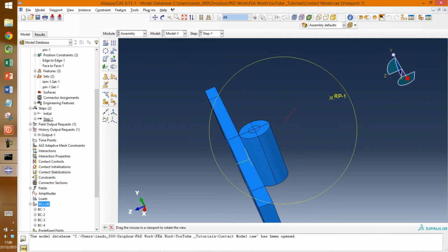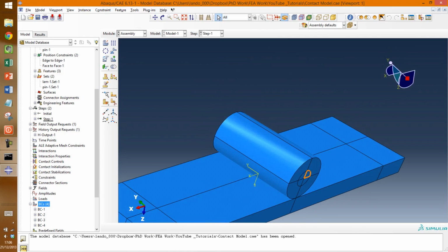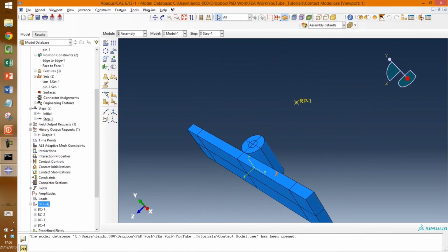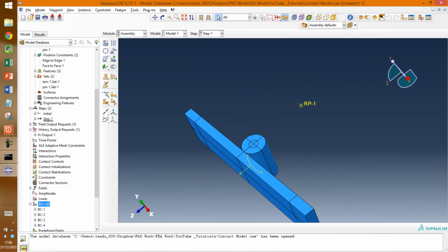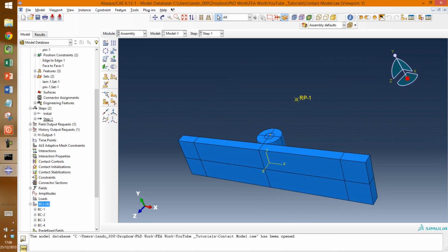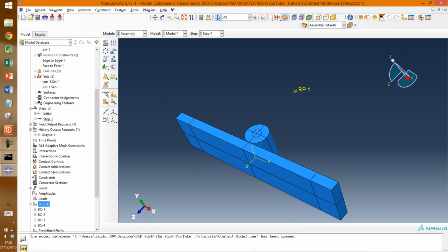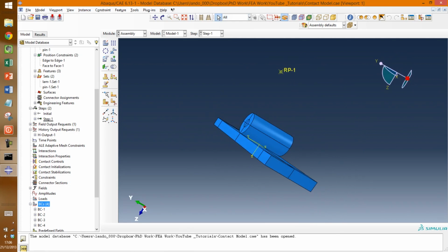So essentially what I'm going to do here is define a relationship between that point and the base of the loading pin. So basically if you tell that point to move 3.5 millimeters in this direction, the loading pin will do the exact same. And I can extract load displacement data from this. So it'll tell me the force that manifests itself on this pin as I'm loading by that certain displacement. And it's just a neat way of doing it. So I've this put in place.